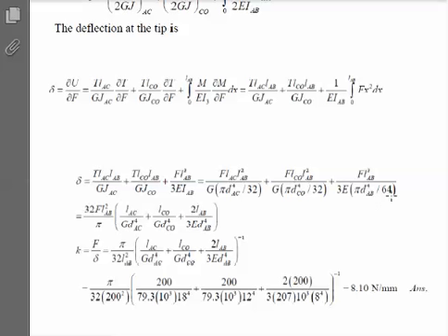So we make that substitution, and the rest is just algebra, crunch and crunch down to the deflection. And now finally, I guess this problem asks for stiffness. Stiffness is simply K, which is force over deflection. So here's our deflection equation. We'll take the force and divide by this thing, which means take the force and multiply by this thing raised to the -1 power.